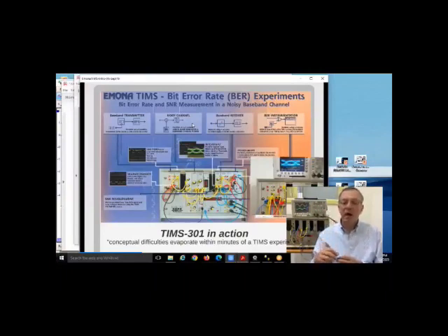We have a true RMS voltmeter, or the virtual instrument, which measures true RMS voltage. So the student actually measures the noise coming through the channel, the noise voltage. They measure the signal voltage. And from that, they do the 20 log calculation to see where this dB number comes from.